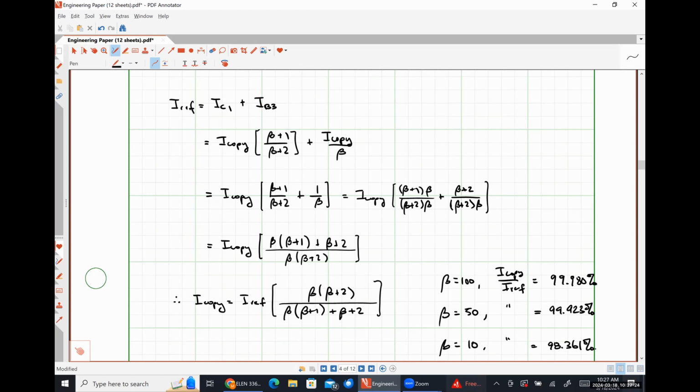We're going to find effectively that the voltage gain of any amplifier can be expressed as just the product of R out and the short circuit transconductance. So the larger that we can make R out in any case is going to give us an increase in our voltage gain effectively. So a couple of different ones that we do.